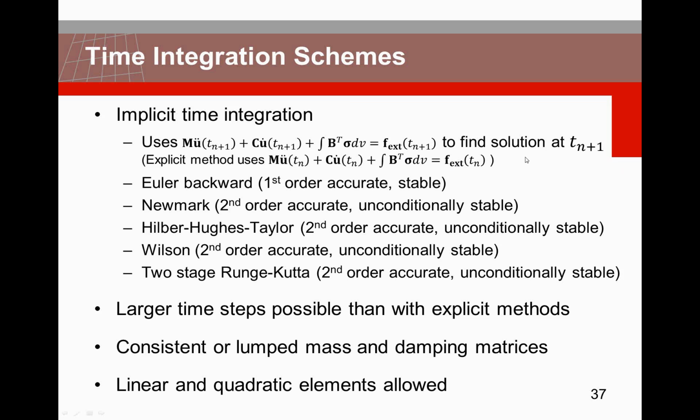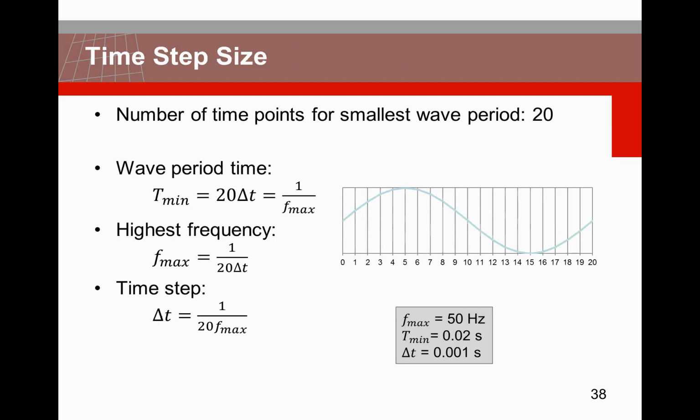But as I said, any method should in the end come to the same solution. The way you do it should not matter. What we have seen earlier with respect to the element size and waves also applies to the time steps. To be able to see the response correctly for a certain point, you need sufficiently small time steps to really represent the response.